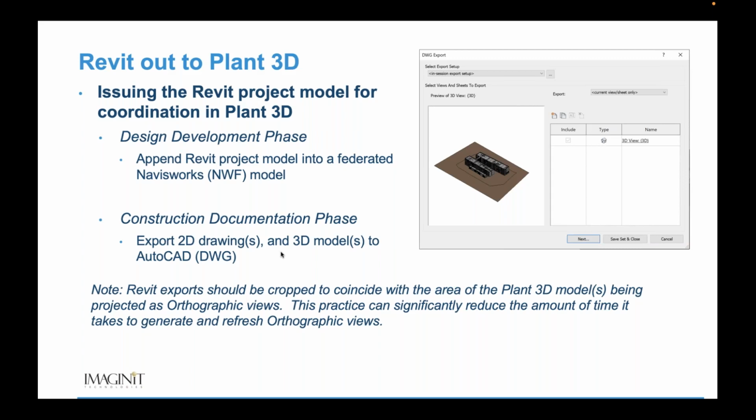If you simply export the Revit model and overwrite the original file in the project folder where it exists after it's already been added to the project, that should be all that you need to do. You won't need to add it back to the project every time. A simple overwrite of the base file in the plant project directory will allow me to update that information.